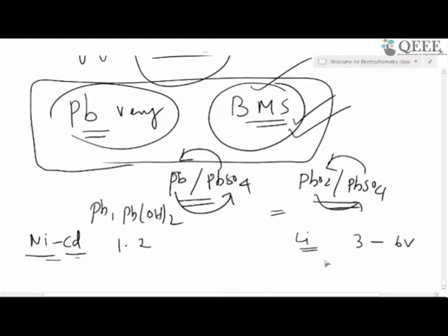But the shelf life of lithium battery is very good, and cycle life or cyclability or rate capability, that means how fast or how slow you can charge, the rate capability is also very good with the lithium batteries. Hence you can consider lithium batteries better than the nickel cadmium batteries. Moreover, cadmium is associated with some environmental concerns and things like that.